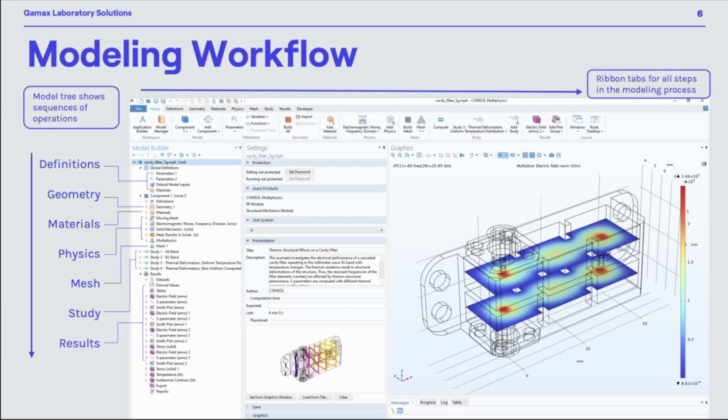At the very end, you can post-process your results at the results node. So that's technically and logically the last part. When we stop, we investigate the results, and we can make conclusions whether we have the right boundary conditions, right mesh settings, and so on and so on.